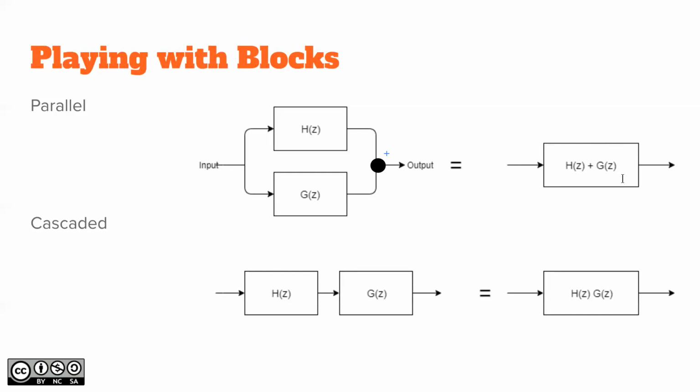So remember the linearity property of the transfer function. It's linear if the system is linear, and that means that you can then do addition either on separate systems or a system put together. Sometimes it is better to break out a system into smaller parallel systems, for example, to speed up the process in a multiple processor system. So you calculate the output of the system in 2 different processors and then add these results together. Sometimes it might actually be faster to do it like that. Not always, but sometimes.